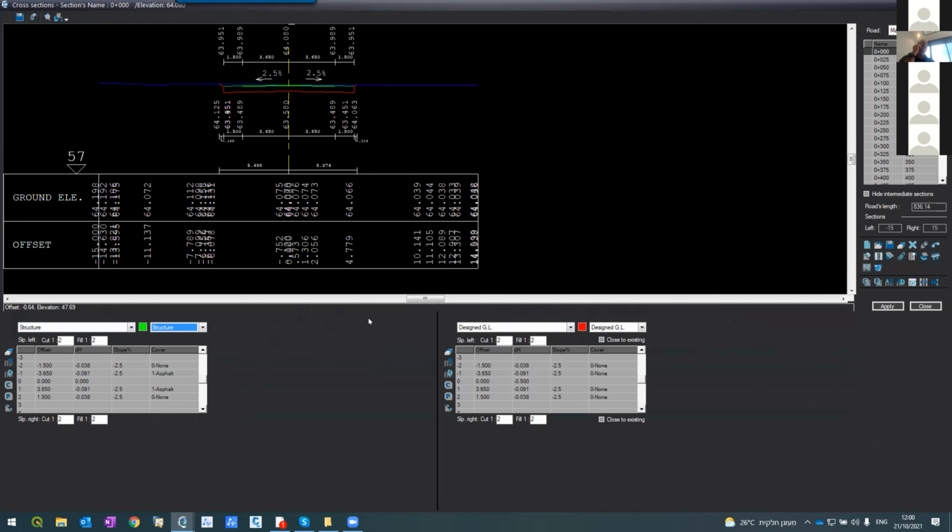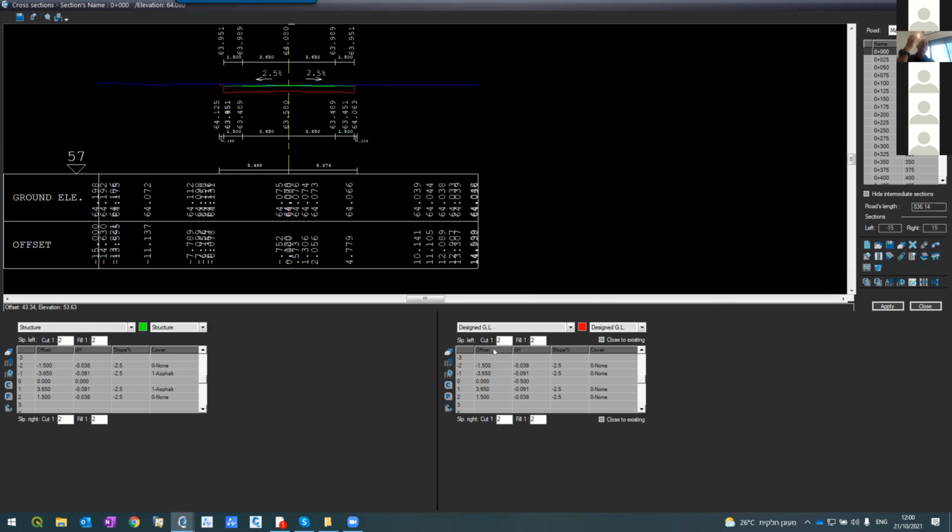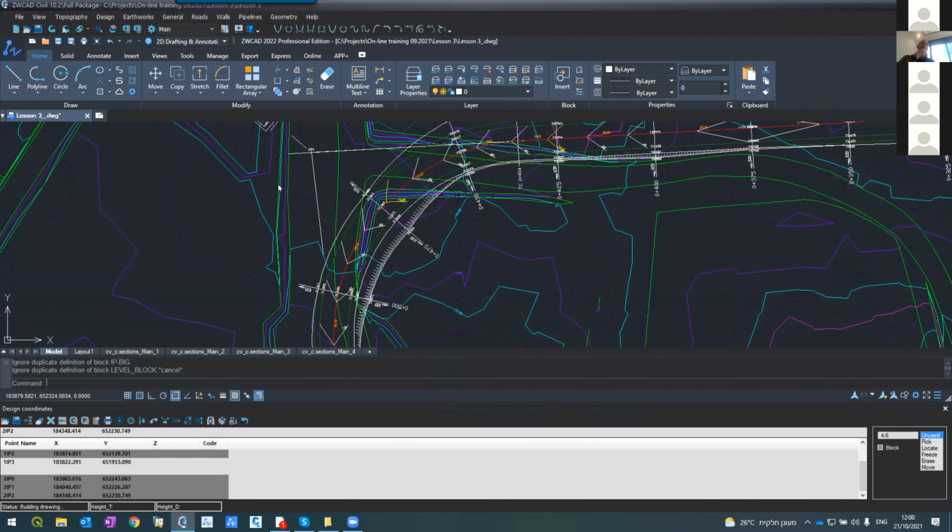It's too complicated to enter everything into this training. So yes, generally here, you open and create sublayers, for example, to the structure. You define a new sublayer, and you can say it's sand, 80 cm or whatever, and then it will affect automatically.